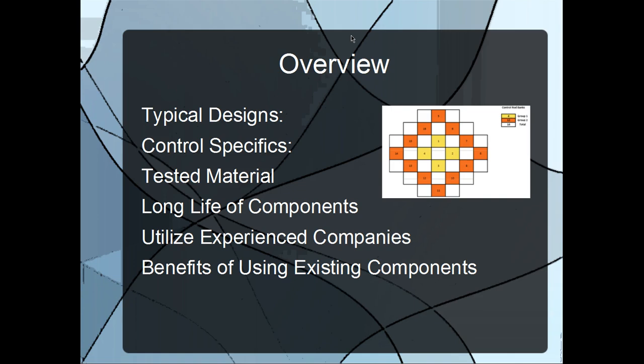These CRDMs are organized into 16 control rod clusters broken into 2 controlling groups situated to provide greatest control and minimal power peaking. The long-standing availability and use of these standardized CRDMs provides the power module with readily available and lower-cost primary components, allowing for an overall lower price tag for manufacturing and maintenance of these units. Utilizing prior tested and operated designs also adds to the margin of operational safety for this newly devised reactor layout.